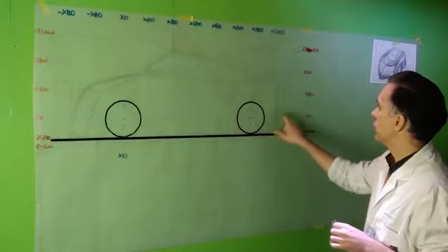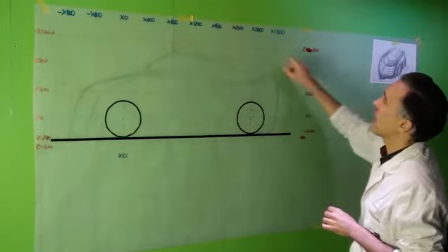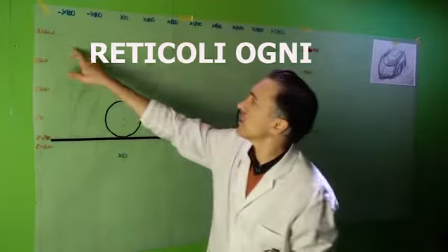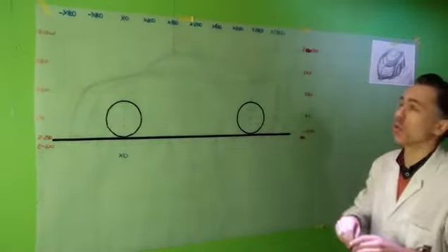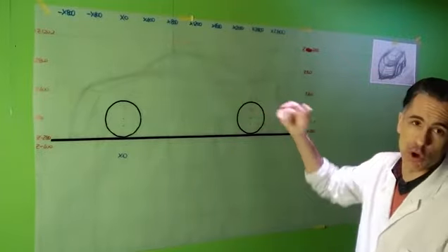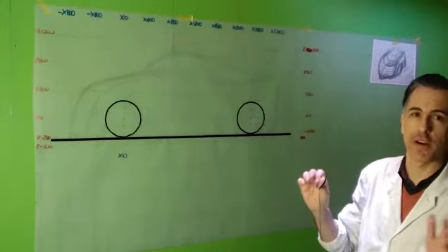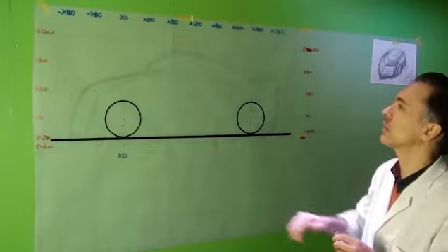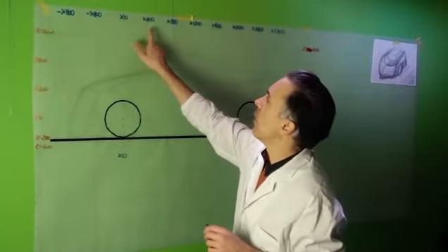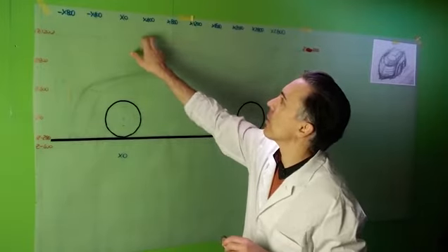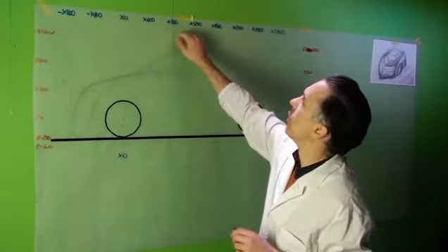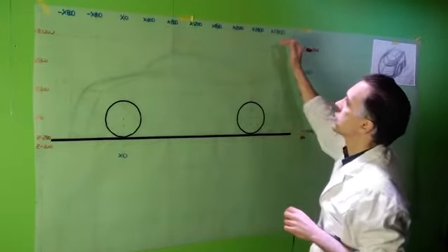As you can see, I have on the wall a transparent paper, a layer, and I have already drawn this grid, and between each line there are 10 centimeters, and this is the measurement for a 1:1 scale model. But I will work on 1:4 scale, and therefore it means that on each line I will write the measurement of the scale that I'm going to use. So I will have a line every 400 millimeters.